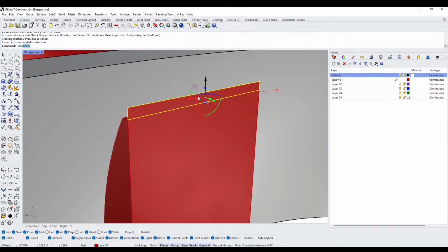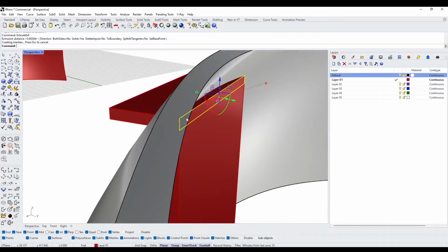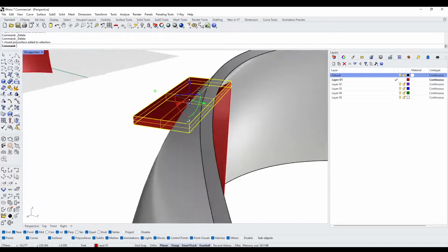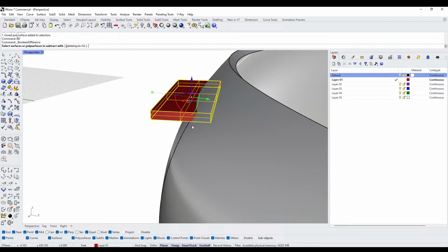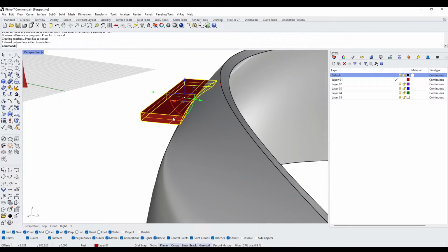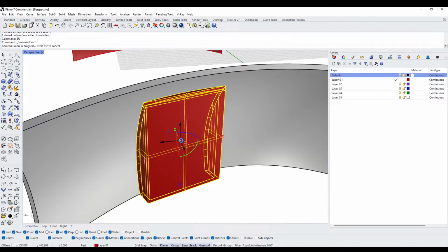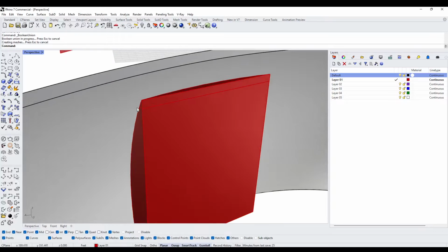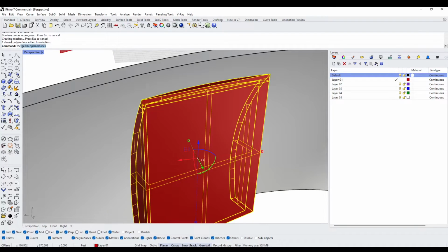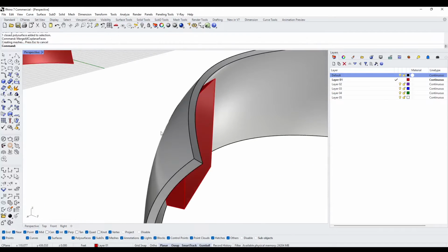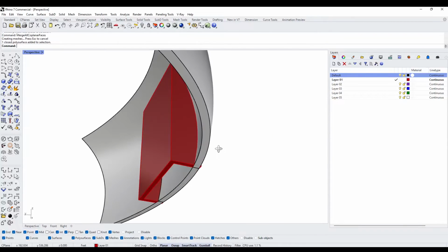and extrude surface out this way, creating like the little bit of the roof that it kind of needs. So subtract it with Boolean difference using the outside shell. And now these two I can join using Boolean Union, and then use merge all coplanar faces to get rid of that little crease. And now we can do that again here.